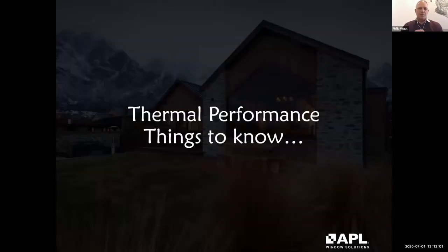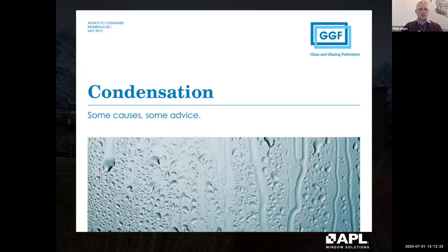So we'll just get back into thermal performance. Thermally broken windows are used to reduce significant conductive transfer of heat through the aluminium. So what it's doing, obviously, it's isolating the outside surface of the window system from the inside. And that has beneficial effects to the window system itself and the internal environment.